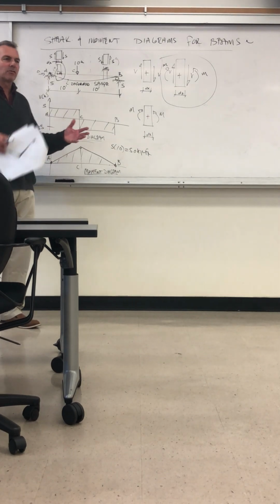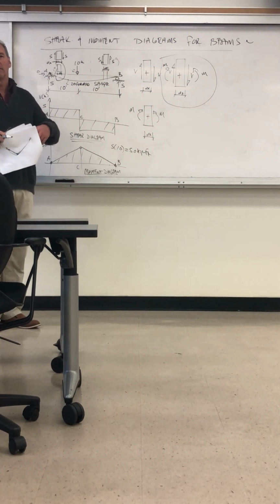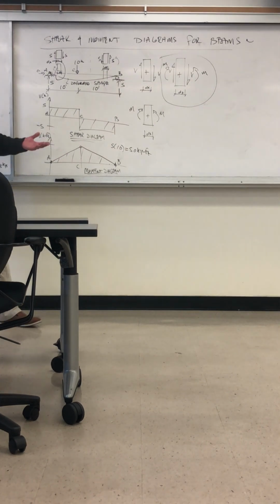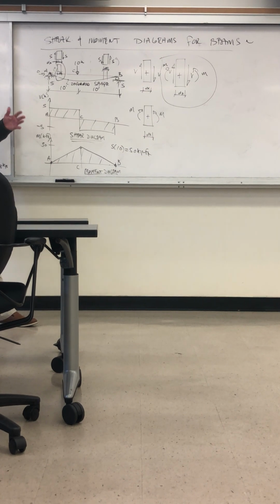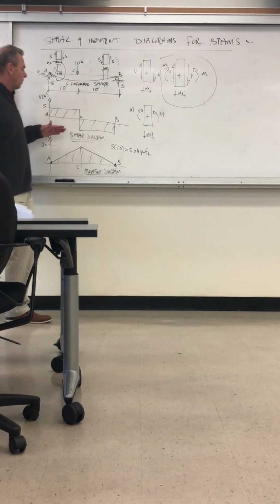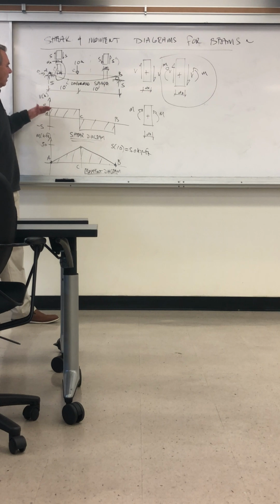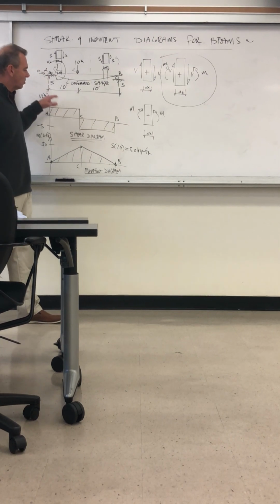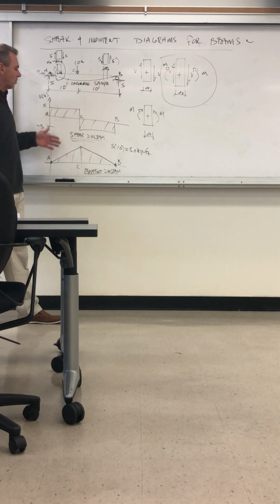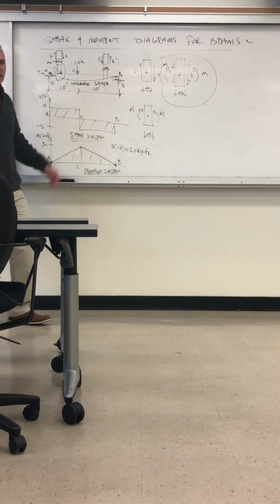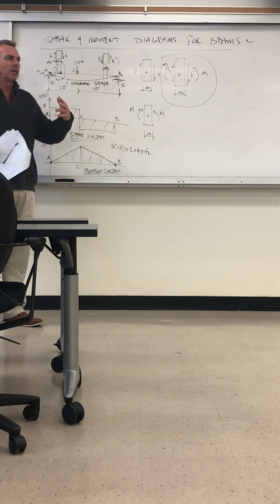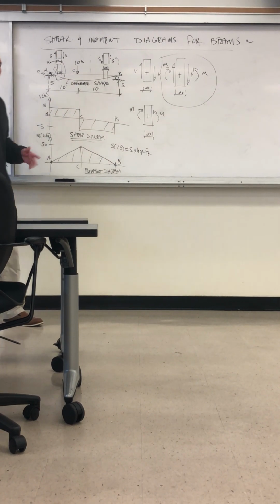So you design your section, different size, different amount of steel reinforcement inside it. If it's reinforced concrete or pre-stressed concrete, or a steel section, you design it and then you can determine the capacity. And then of course you plot on top of that the capacity in moments and shears. In all cases, the capacity has to be greater than the maximum demand. Otherwise, that location where they cross over is where it's going to yield and fail.